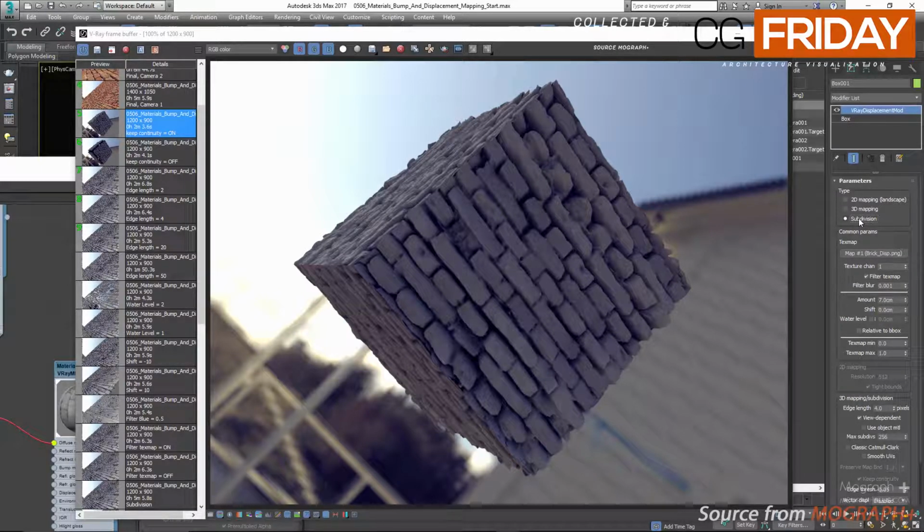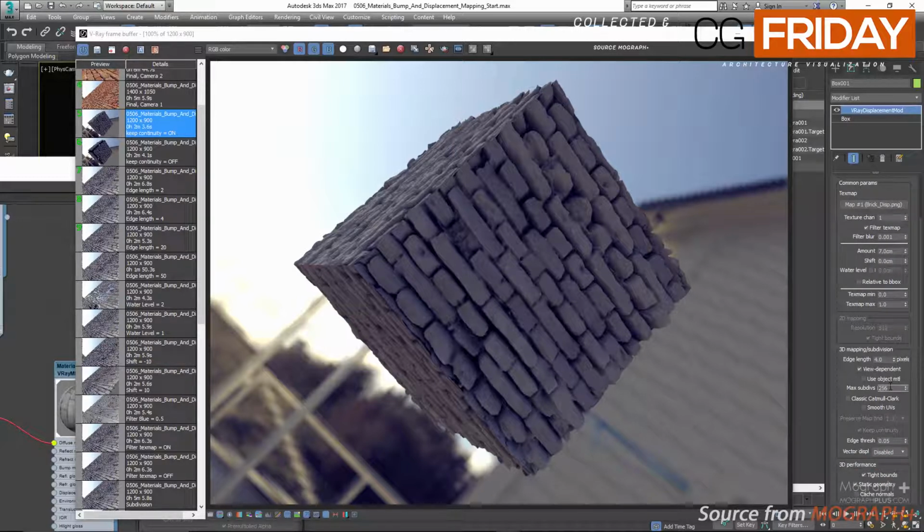First, there is this max subdivs, which controls the maximum subtriangles generated from any triangle of the original mesh. So the actual number is the square of this number, as with other subdivs values. So make sure to cautiously alter this number all the time.